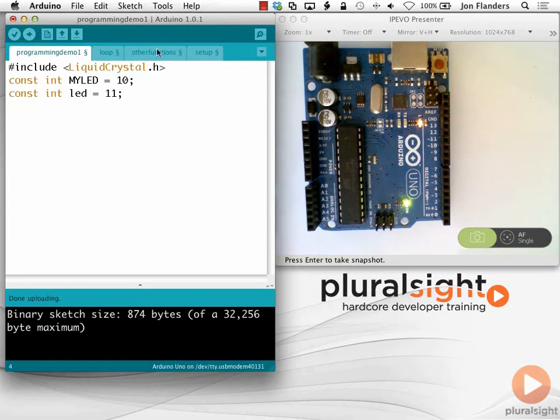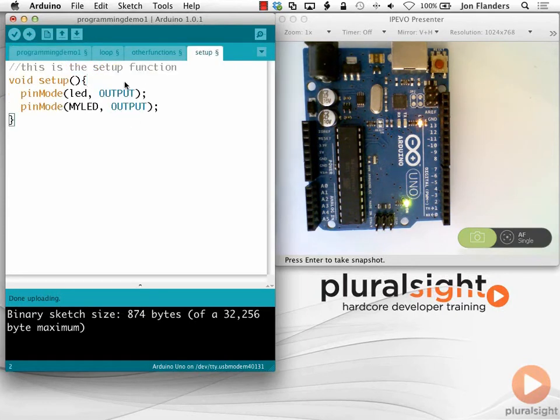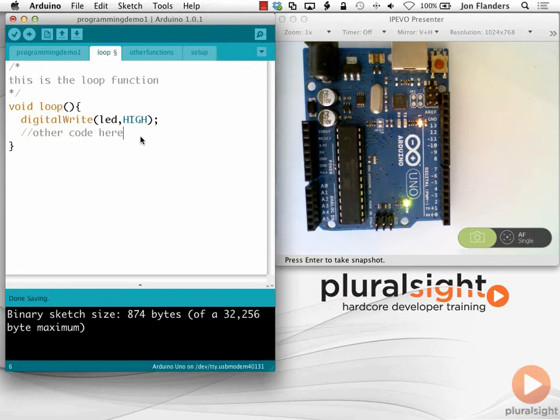So this is where the serial object is really helpful. If I say Serial.begin, I can specify the baud, which is 9600. And then inside of the loop, I can say, let's do a delay of a second. And then I will say Serial.println, end of loop. And maybe I'll put in a beginning of loop.